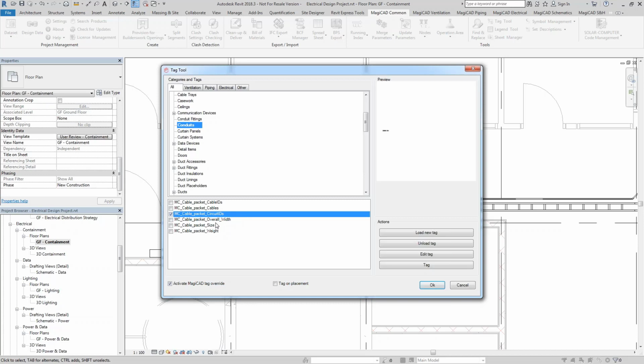The size would be the cross-sectional area. So if you were doing this as a fill value within trunking or something similar, then you'd be able to use this to give you your overall fill size. Your weight, so we give you the ability to input the weight in kilograms per meter. So you'll be able to detail that as well if that's a concern for the amount of weight on the cable tray itself, or the hangers that are holding that cable tray up.